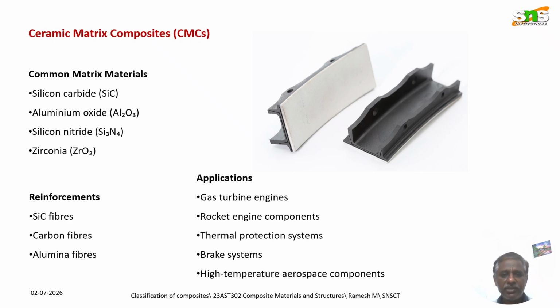The main purpose of developing ceramic matrix composites is to overcome the brittleness by incorporating a suitable reinforcement into the ceramic matrix. A ceramic matrix composite generally consists of a continuous ceramic matrix and a reinforcement phase. The matrix provides high temperature stability, hardness, oxidation resistance, and environmental resistance, while the reinforcement improves the fracture toughness, damage tolerance, and resistance to catastrophic failure. The reinforcement also helps control the propagation of cracks through the material.